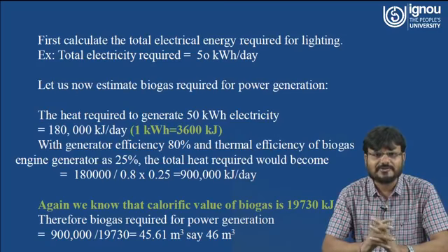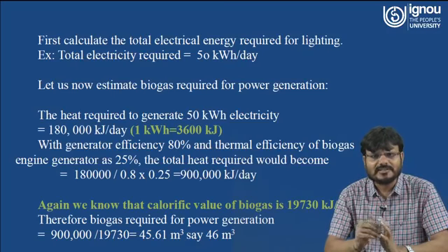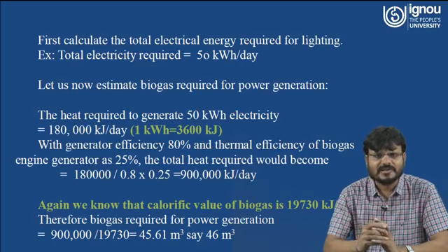And now here I am assuming that the generator efficiency of this biogas plant is 80% and the thermal efficiency of this biogas engine generator is 25%. So the total heat required will come around 900,000 kilojoule per day, right? Now again we know that the calorific value of biogas is 19,730 kilojoule per cubic meter.